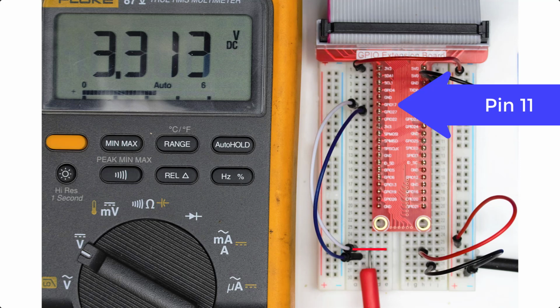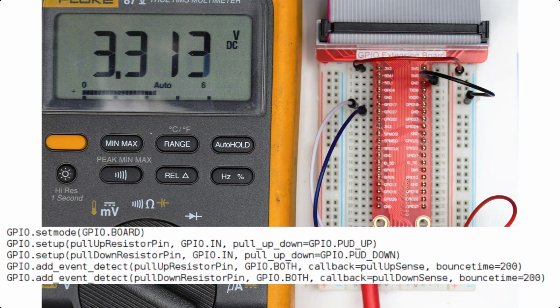But you can see that essentially what I'm doing here is I'm measuring the voltage of pin 11, GPIO 17. We also need to connect the black meter lead to the ground bar. So mine's tucked away down here, but you can see it pointed to by this black arrow. So we have our black meter lead on ground, and our red meter lead is reading the voltage at pin number 11. I pulled up the setup portion of our code to help remind us of what is happening here.